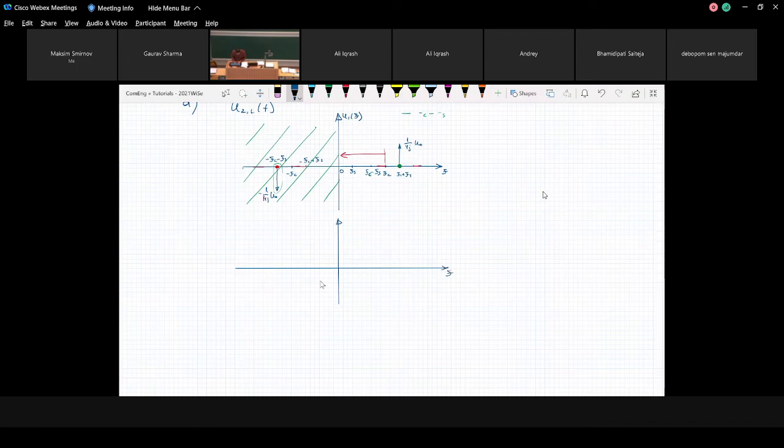We have frequency F plus Fc, and we have only one delta pulse at the frequency Fs, with magnitude 1 over 4j U0. And now we have to normalize it. We have to multiply, because it's a signal. It's not a transfer function, it's a signal. And what we do to normalize a signal when we perform a low-pass transformation is multiply by square root of 2. And after this step, we get